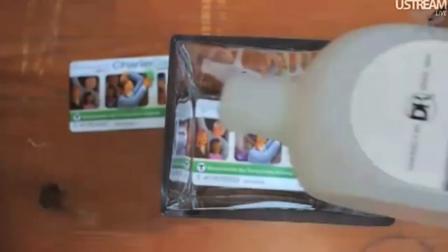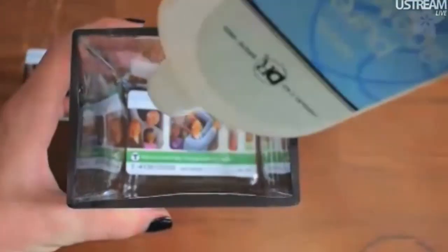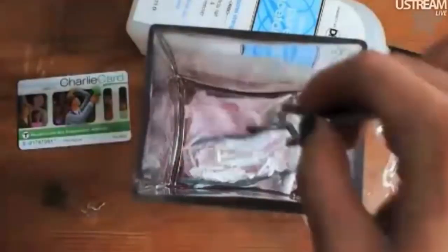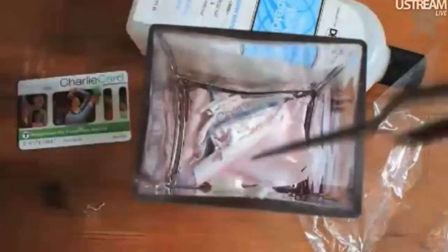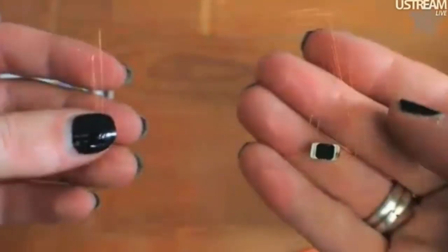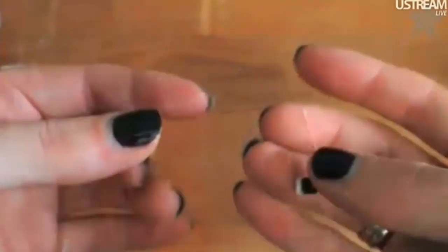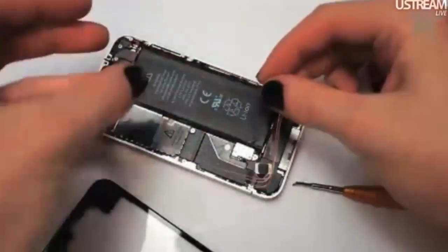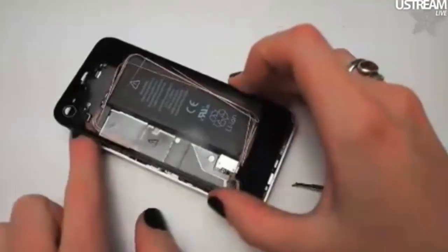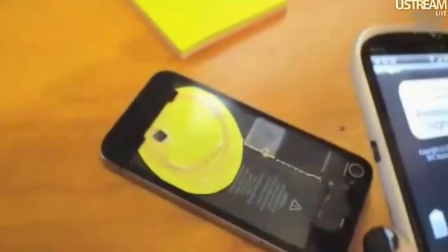We wanted to try to put this RFID transit card inside the iPhone, but the plastic was too thick. You can dissolve the plastic away with acetone and then remove just the antenna and chip from the plastic mess and put that inside the phone. Although the wire looks bare, it's actually enameled antenna wire and won't short out anything inside your phone.